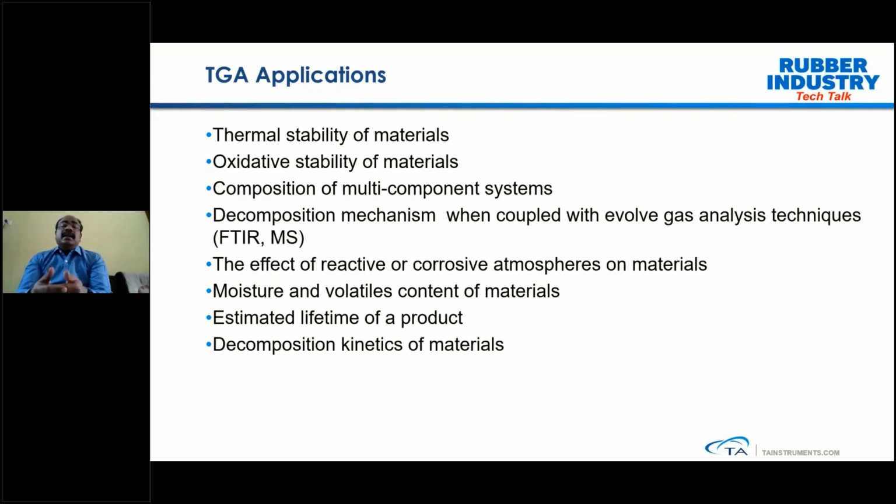And then as I told you, with TGA we have the option to change the atmosphere. Most often studies would be performed in a nitrogen atmosphere, but sometimes you can also do it in a reactive atmosphere, and then you can see how the material is going to decompose in a particular atmospheric condition. Apart from that, we have moisture and volatile content of the material, estimation of lifetime of the product, and also we can understand the decomposition kinetics of the material.